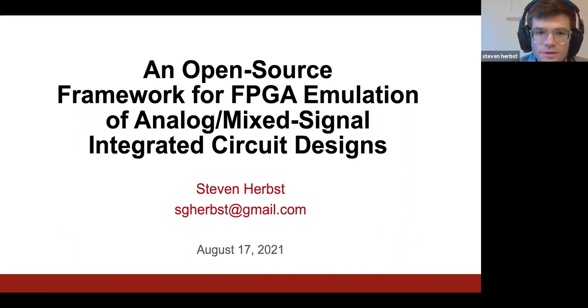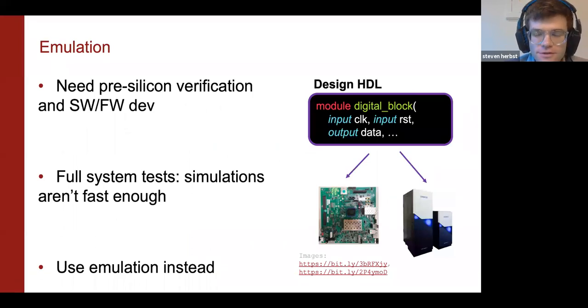All right, yeah, so as Rob was mentioning, the verification topic is really important for chip design, both for digital design as well as AMS design. And in addition to that, before the chip comes back, we also want to be able to interact with the design to develop software and firmware so that we can reduce the overall development time for the product. So the unfortunate thing is that when we're working with a pre-silicon design, if we want to simulate the whole thing, often that's not really fast enough for the work that we want to do, whether it's software development or running very long tests like booting an operating system or verifying operation over billions or trillions of cycles.